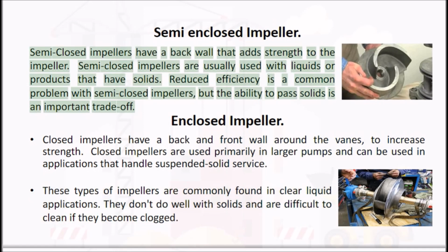Semi-closed impellers have a back wall that adds strength to the impeller. Semi-closed impellers are usually used with liquids or products that have solids. Reduced efficiency is a common problem with semi-closed impellers, but the ability to pass solids is an important trade-off.